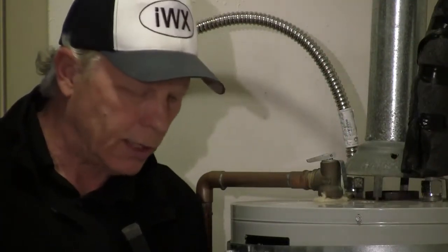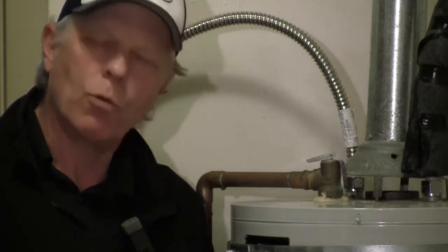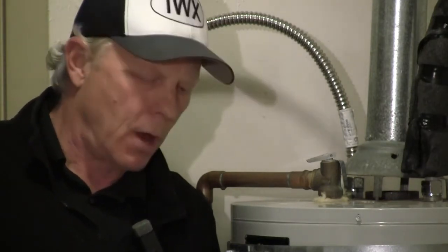Okay, we're on line 8 of combustion appliance zone testing, and this is where the candidate will check one appliance for spillage under worst case conditions, and then state the time limits for spillage based upon the current version of ANSI BPI 1200. So I'm going to go ahead and do that next.